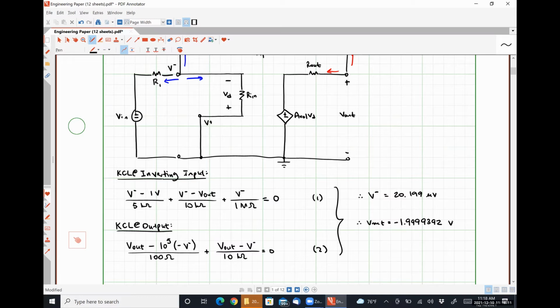When we deal with an ideal op amp, which we are not yet doing, we will find that the output voltage is nothing more than the closed loop gain times the input voltage. But we don't yet know what the closed loop gain is. We only know the open loop gain. So if we were dealing with just the open loop gain, we'd be facing that same conundrum that we talked about at the very beginning of this class, okay?